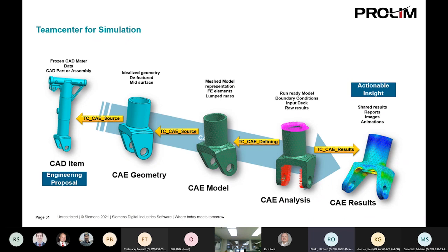So if you think about the designed geometry that the CAD team has created, or maybe you yourself have created, maybe it looks something like this, part of an aircraft landing gear. When you then go to perform simulation, there is a level of simplification or at least some sort of modification that needs to be performed on that geometry before it's ready for analysis, right? So maybe you remove some of the parts that aren't needed. So straight away, we're deviating from the original CAD geometry.